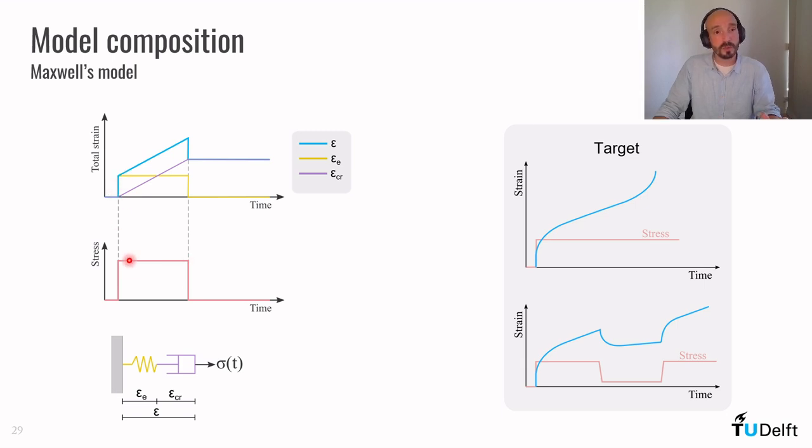If the stress is constant, it will stay constant. When we remove the stress, it recovers completely. And the dashpot deforms at a constant rate. When we remove the stress, it stops the deformation and doesn't recover. And the total deformation of this model is given by the summation of the individual deformations of each element.